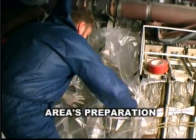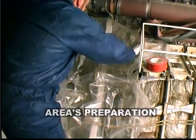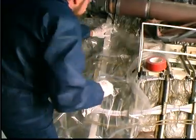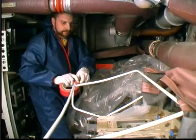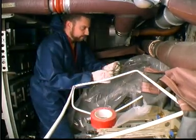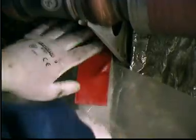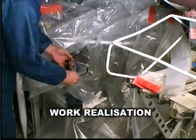Before making a maintenance modification, you first have to protect the area where you will be working. Plastic film must be applied on the area to protect. Maintain the protective plastic with adhesive tape. You can now start your repair. Protect yourself with glasses and gloves.